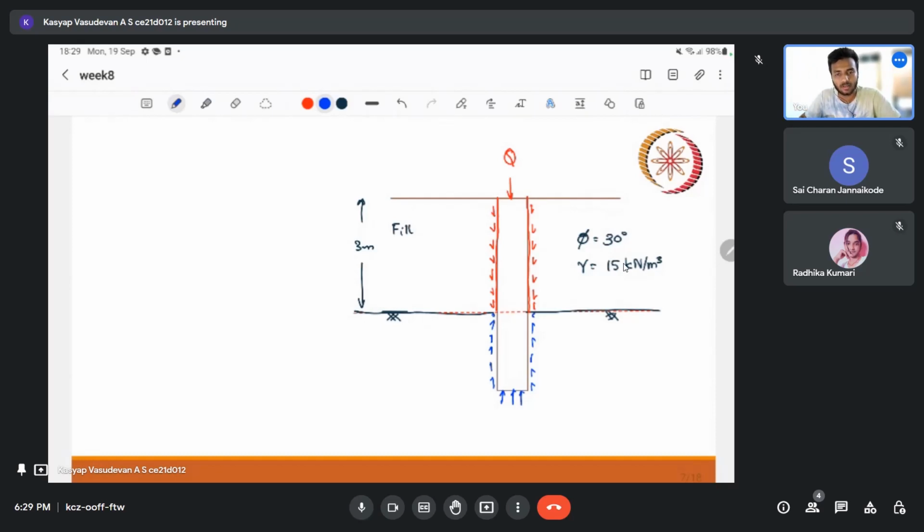So let us say this is the capacity of the pile, and our negative skin friction is, let us say, QNF. But here we are just asked QNF, so we just need to find the shaft resistance in that portion. That is nothing but our basic equation that we had discussed well before. We have K, the horizontal pressure coefficient, into sigma, tan delta, the interfacial friction, and the area AS, that is the shaft area.